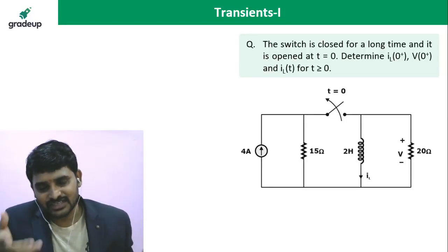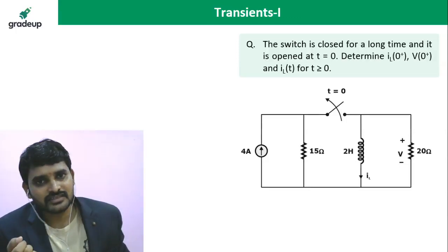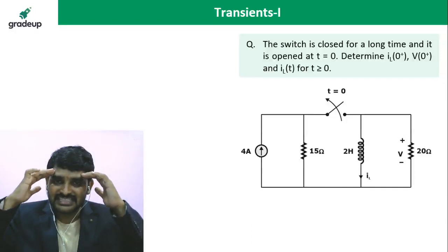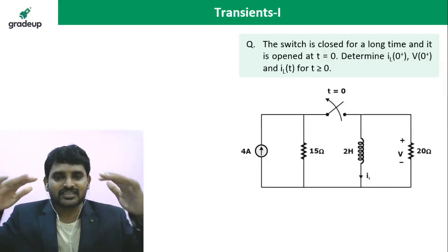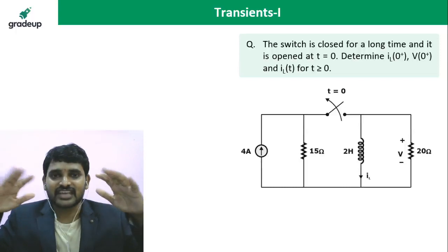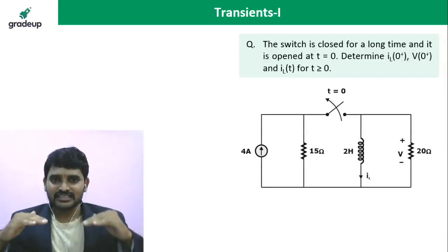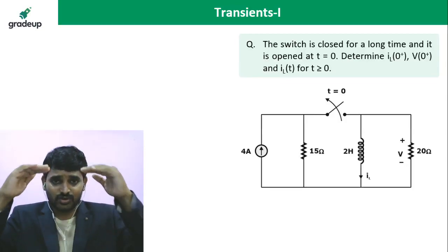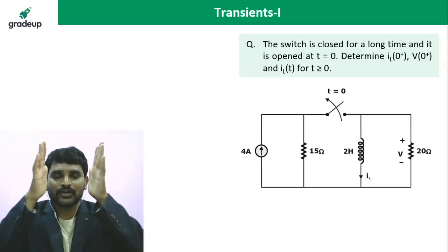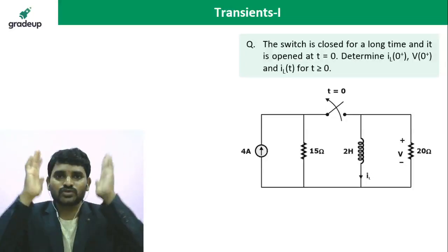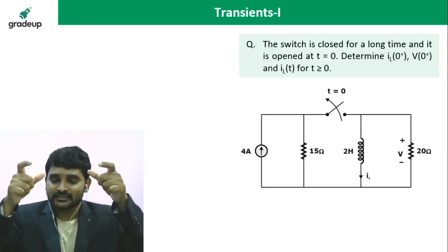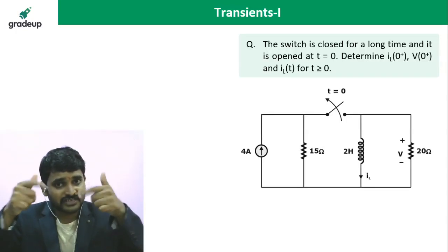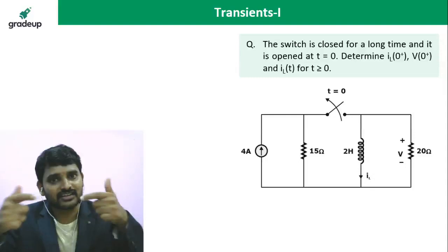Will you get that rush of electrons after 1 second or 2 seconds? Not possible. Why? By the time the capacitor is fully charged, it has stored the charge carriers on the plates. Once the charges are stored on the plate, the potential across the capacitor and the source voltage will be equal, so the potential difference is zero.